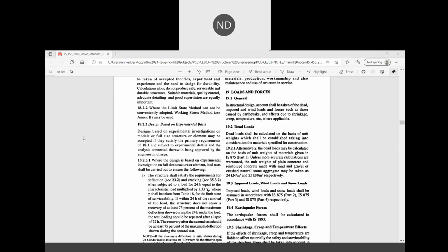Suppose you have some beam, you have some column, and slabs will be there. These will be made up of your materials, like the concrete, okay, and steel will be there. So now, particularly, suppose I talk about this particular column, what is the dead load of it? That means the load coming from these members, column one, column two, and then this beam one.